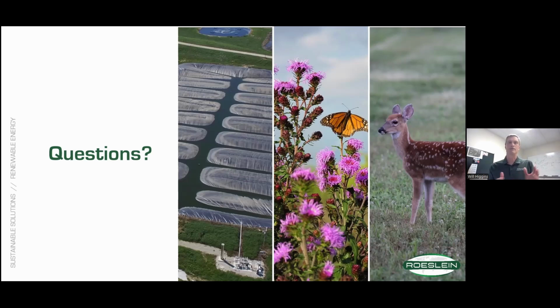And so you've got a shorter window to actually consume all those volatiles and make your biogas. And that leads to needing a larger lagoon. So you hold all your manure longer to get it through that cold period. Because if you don't hold it during the cold time and it passes through the digester, you lose it, right? If it leaves your digester before it gets warm enough to get digested, well, that was your shot.